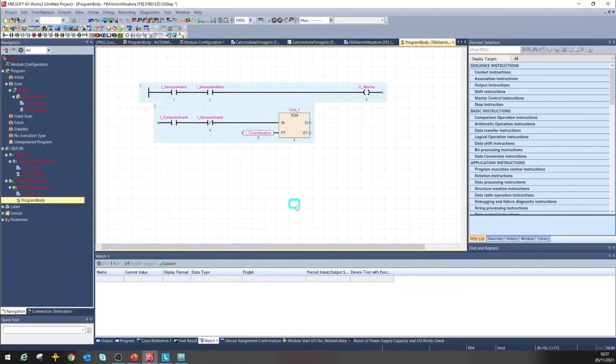We now define an input variable of type time, and in the ET, the elapsed time, is determined. We are interested in knowing when this time passes under these enabling conditions. So the output, which for us means alarm, is valued if within this time the sensor forward has not been identified.